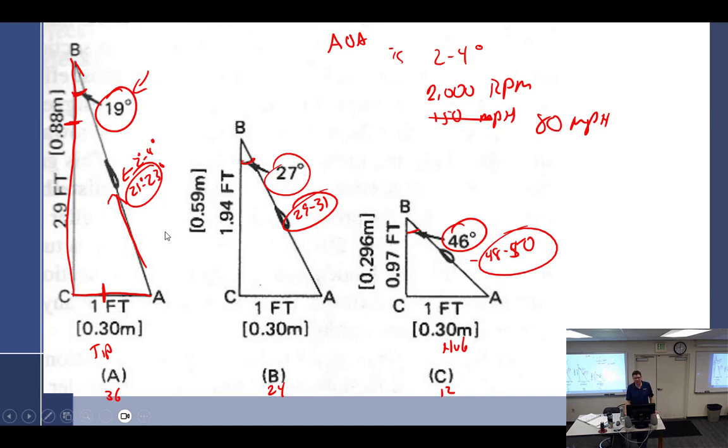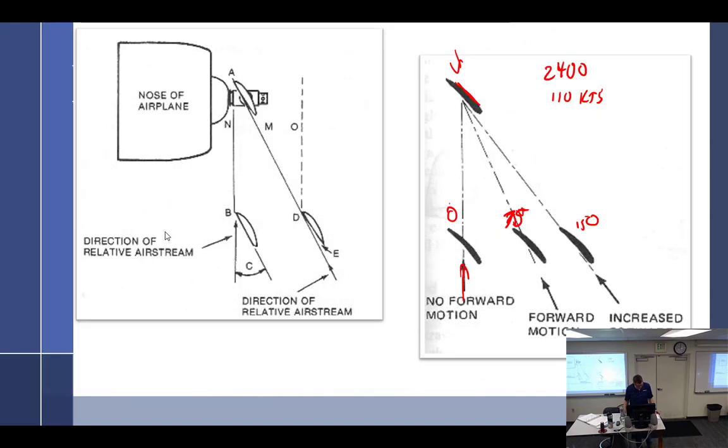What I need you to understand is why it twists, and try and see that in your mind. It's going around at a certain RPM and forward, so that around and forward gives, it's not this way and it's not this way, it's somewhere in between, and each little station has its own little thing that's going on. And then also this right here, we see, angle of attack will change with any RPM or aircraft speed.